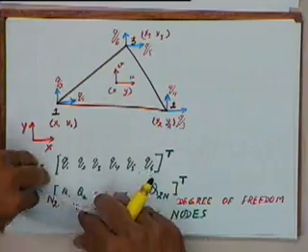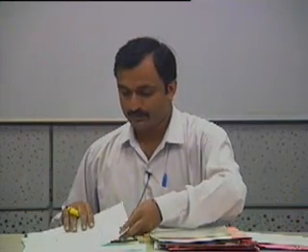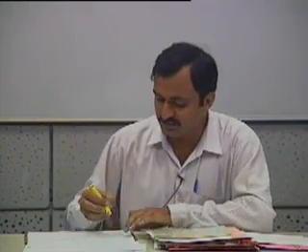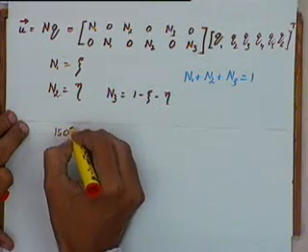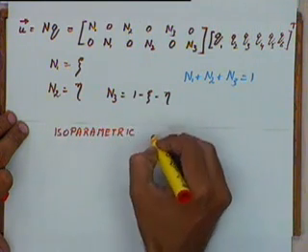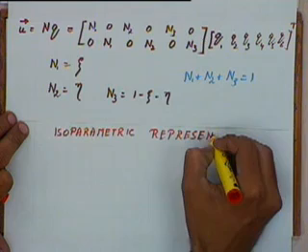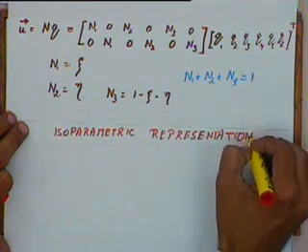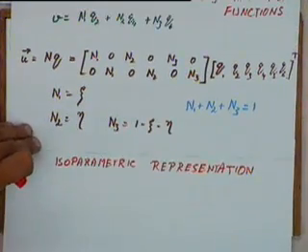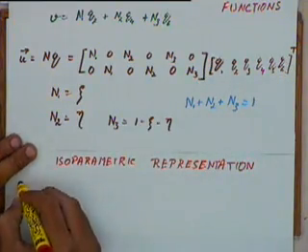So relating these two, we will take what I explained earlier, an isoparametric representation. If we assume an isoparametric representation, we have said u is given by this expression, so x also has to be given by the same expression.